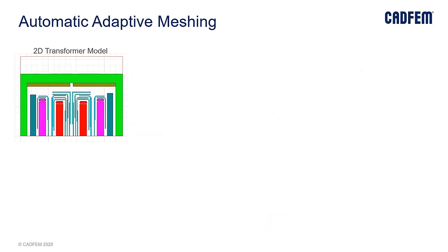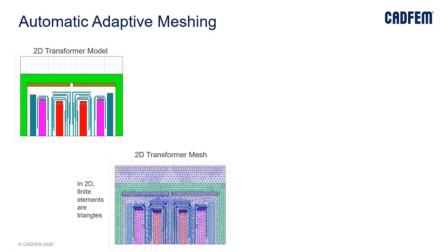As I mentioned, apart from the previous capabilities, there are a few more capabilities which will help a lot for these transformer simulations, such as auto adaptive meshing technology. Basically, the quasi-static solvers like either magnetostatic or electrostatic, and the steady state or eddy current solver use this auto-adaptive meshing technology. When I say auto-adaptive meshing technology, this will automatically create the mesh to increase the amount of accuracy. So the only thing as an engineer we need to tell it is what the energy error convergence must be.